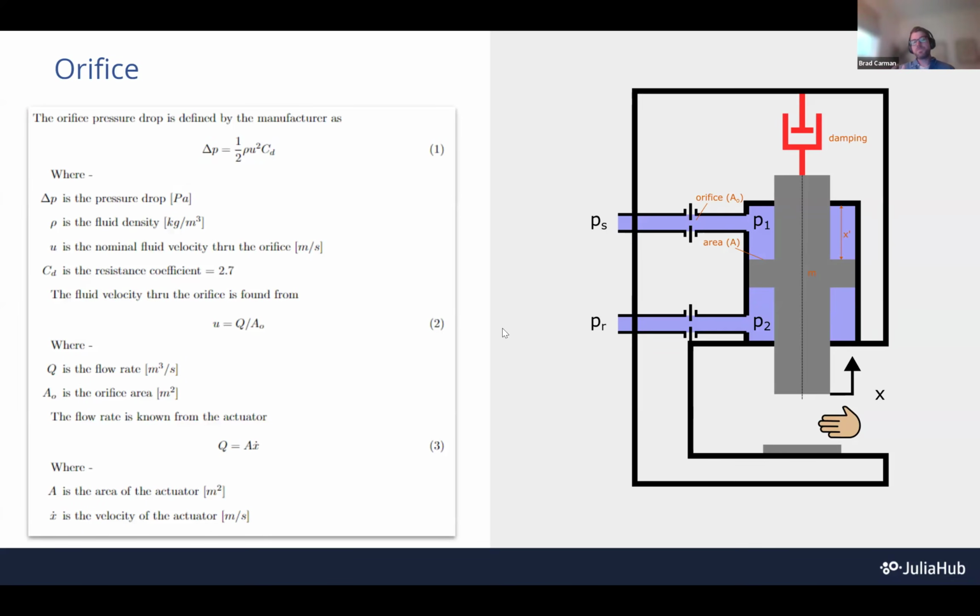Okay, so we do some research, and we find a distributor who sells exactly what we're looking for, an orifice plate that can restrict flow. The manufacturer provides us this information that I'm showing here, which allows you to calculate exactly what size orifice we need.